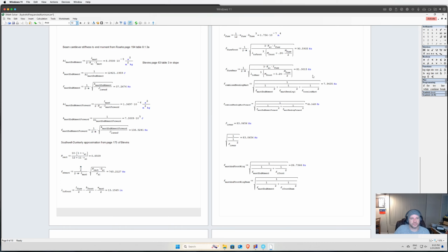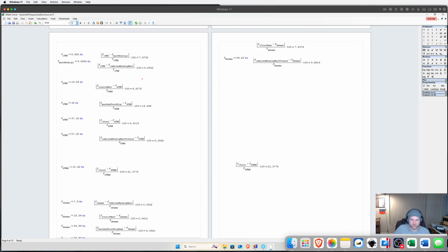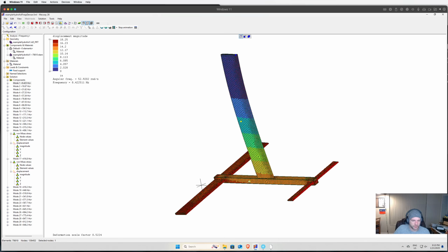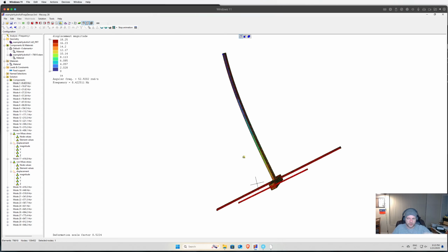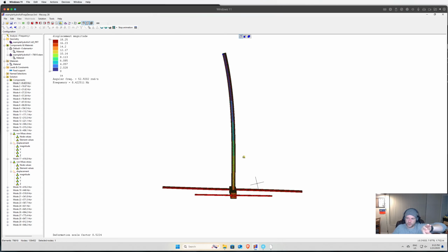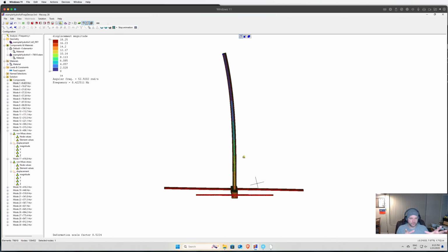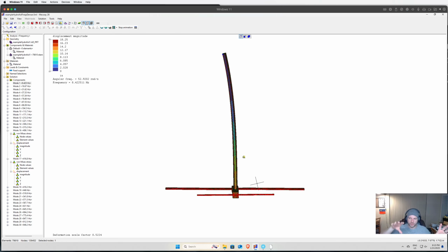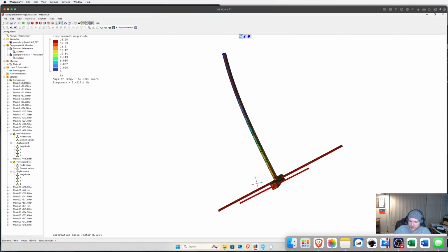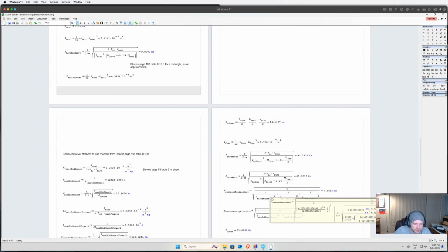So it's actually a combination of not only a bending mode, but a torsional mode or a twisting mode of the shape. So not only do we get a pure bending mode, but there's also this rotation and torquing of this whole moment of inertia of that fuselage and the wings combined. So the mass and everything is causing that mode to drop. And so when I combine those things, I combined the mass and moment, which is what that is.